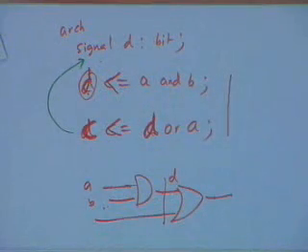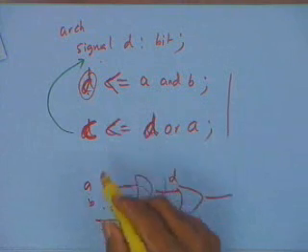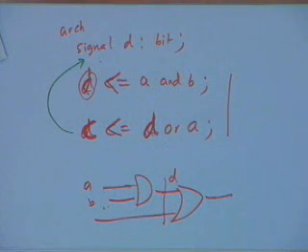So can we assign C equals to C and D? No, you cannot do that. That's the same notion. Then you have two drivers now. So there is a feedback. There are methods, we will see, of course, what happens in case of VHDL. So this I am talking of purely concurrent behavior.